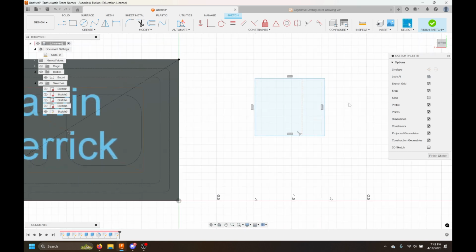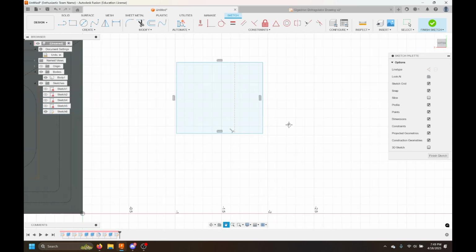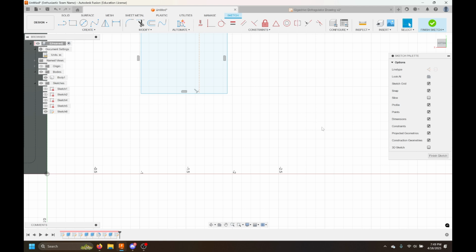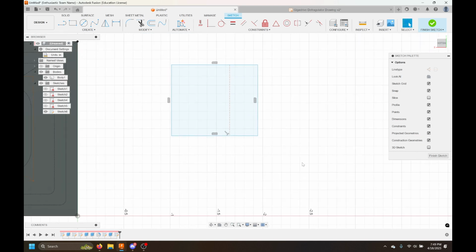Okay. I'm going to show you selection direction. If I select and drag my cursor anywhere to the left, I get this yellow dashed box. But if I go to the right, I get this orange solid box. The best way to remember the difference is that left you select liberally and right you select conservatively.